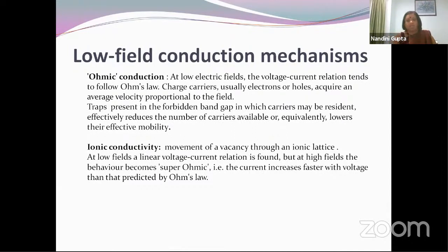At the outset, you have a low number of charge carriers because it's a dielectric, and the charge carriers have enough resistance, so they're not really able to flow through the material very well. And you are removing players from the game. So effectively, trapping reduces the number of carriers which are available for conduction and therefore reduces mobility. This is what happens in the case of low fields.